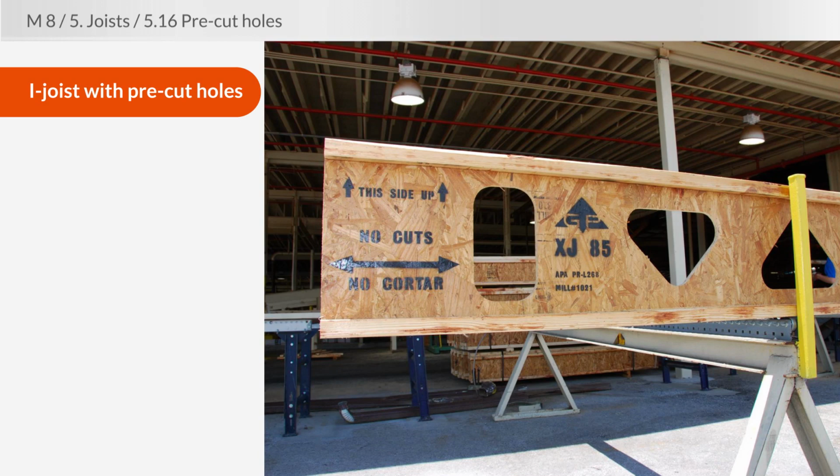Notice also right above where it says no cuts, it says this side up. Not all I-joists will say that, but if they do, they're dead serious. Sometimes the joists are made with a little bit of camber in them, or a little bit of preset curvature to them. And that is to help resist the tendency of the I-joist to deflect and then form a low spot. So if the I-joist says this side up, they're dead serious about it. If you were ever to see an I-joist with the this side up pointing down, that would be a major defect you would definitely have to report.